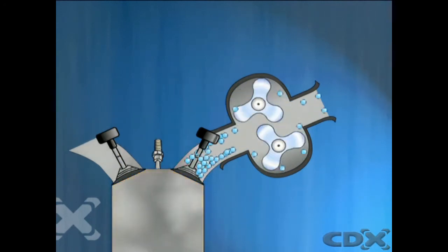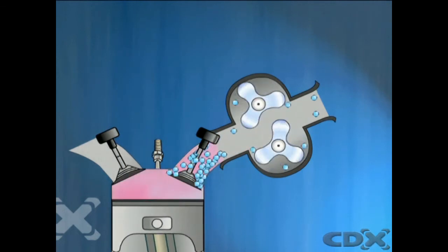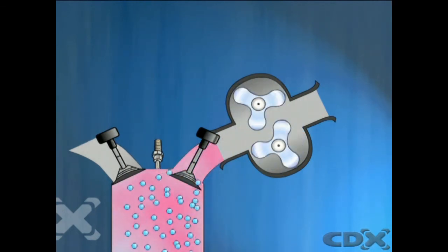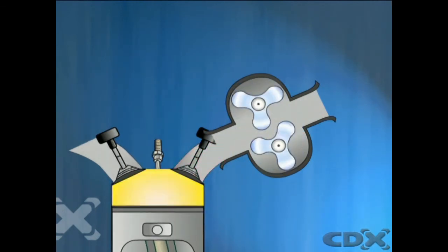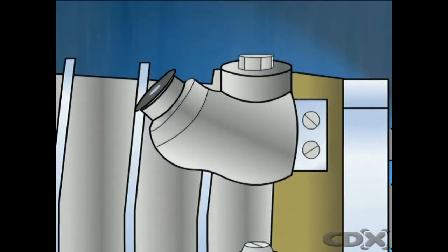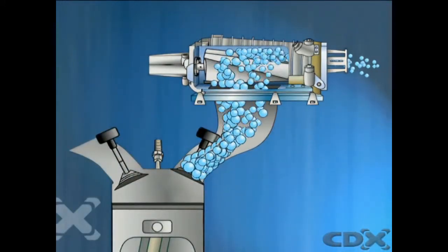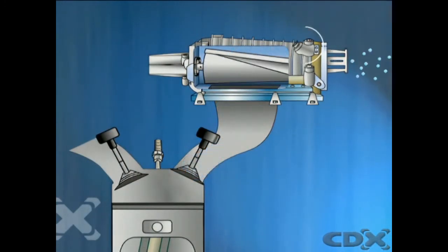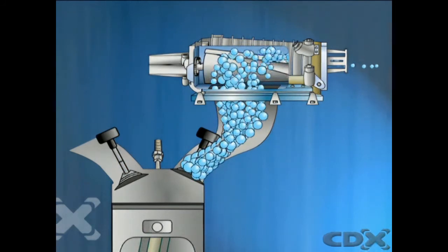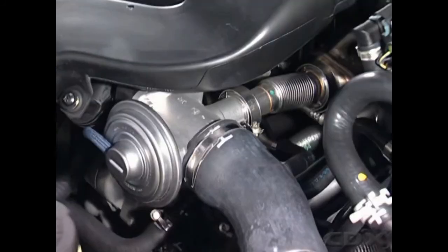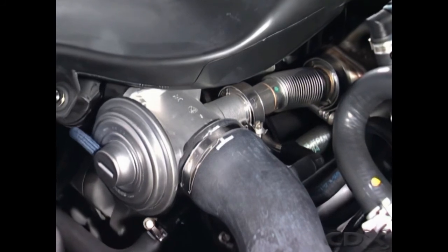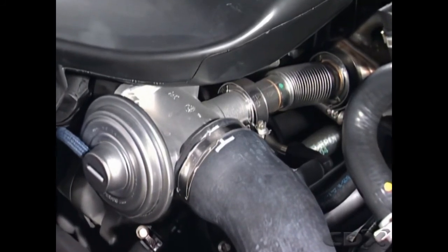Although some of the extra power produced must be used to drive the supercharger, the net result is more total power from the system. The supercharger includes a bypass valve system, which allows the supercharger to idle when high power is not required, turning off the pressure and allowing the engine to run as a naturally aspirated engine. The bypass valve can be mounted remotely or directly onto the intake port.